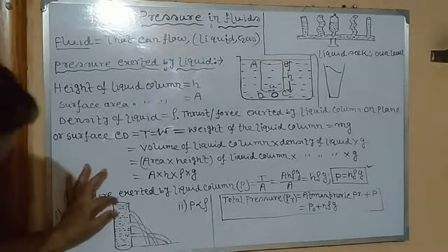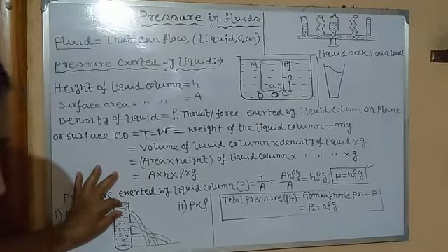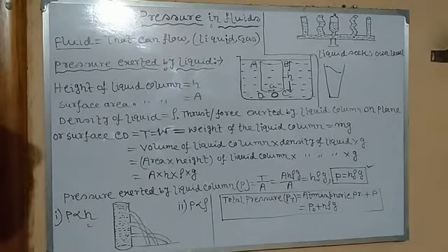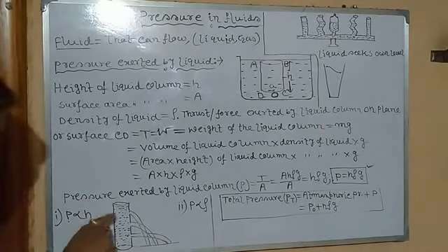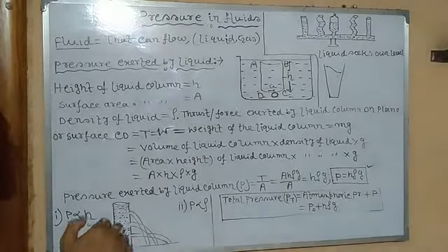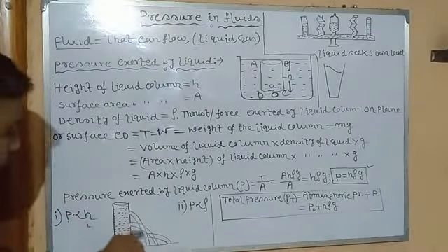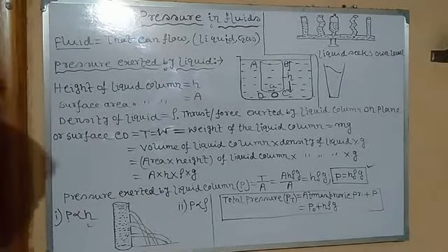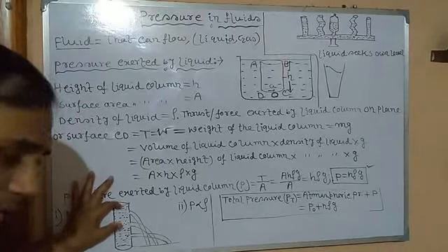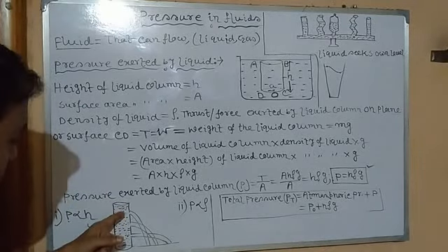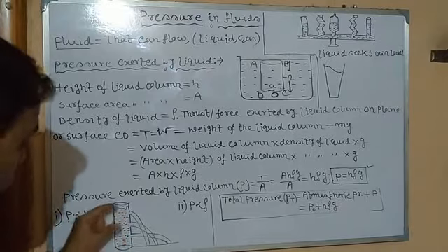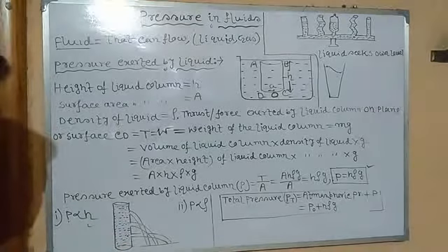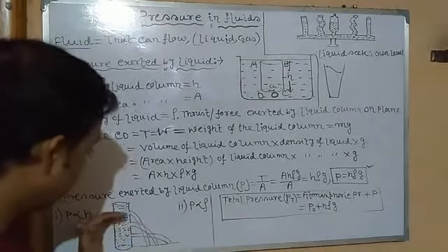Now the height of the liquid, you can see from the free surface, is extremely less. So since pressure is low, velocity is very low, so the water which releases from that hole will traverse a small distance due to its less velocity. Whereas if we gradually go down to the second aperture, its height is slightly greater than that of the upper hole. So its velocity is slightly greater, meaning the pressure is slightly greater than that of the above hole. That's why it traverses a longer distance.